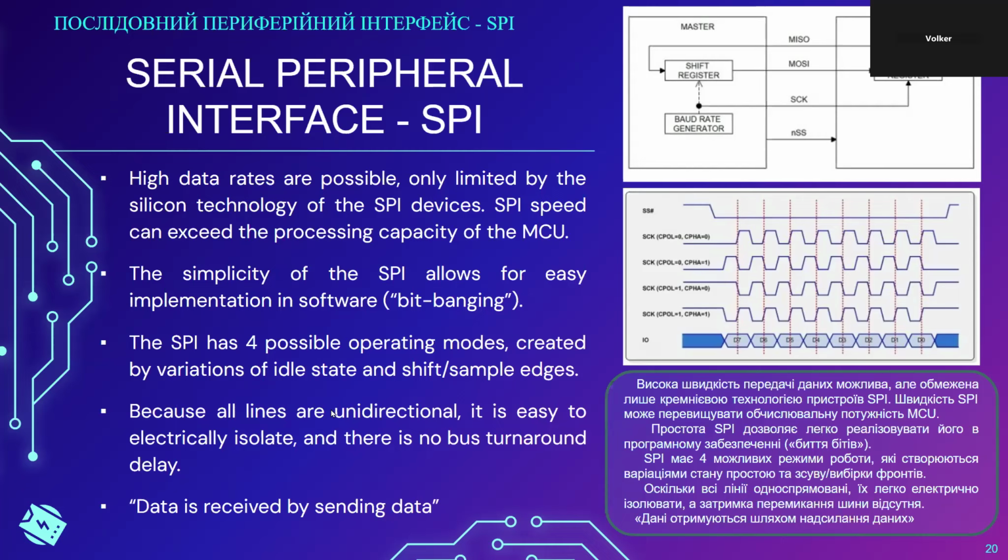It's way too fast. So luckily, the microcontroller is a bus master. The microcontroller is determining the speed of the interface. But for example, a memory device can support speeds that an 8-bit microcontroller cannot use. It doesn't matter really, but I'm just saying this to point out that the SPI interface can be very, very fast. It's one of the fastest onboard interfaces that you can get for a microcontroller.